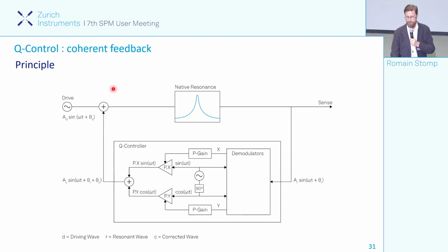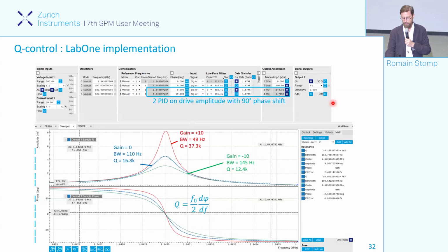This is done at a fixed frequency, and nothing prevents you from continuing the job with the PLL while this loop is running for the resonator change, and then have a PLL with a high Q. Now I will show you this after the break, how it works and how this also changes SNR. You will see this live, but maybe just as a teaser.